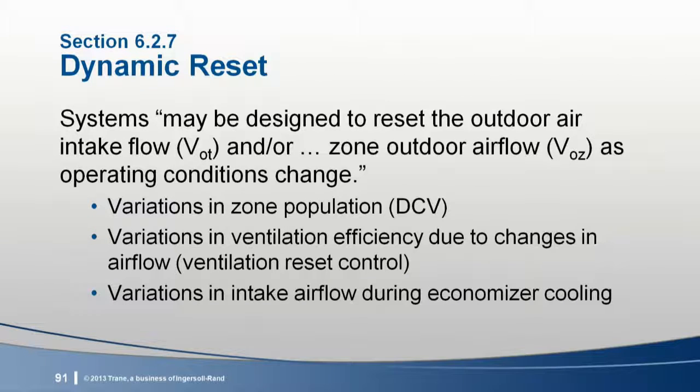Finally, the minimum primary airflow setting for VAV zones may be reset in response to variations in system intake airflow, which occur during economizer cooling operation. This option reduces reheat at the VAV boxes. Today, Dennis will talk about the first 2 approaches, and remember, although the standard mentions 3 dynamic reset approaches, it doesn't prevent designers from using others.